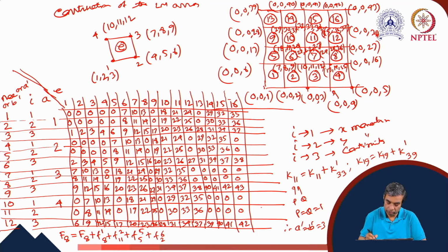Now, I already told you that these values are actually capital P values. So now we have understood that for a multidimensional problem, using the LM array, we can easily perform the assembly process. I have told you KPQ will be 0 if P and Q do not belong to the same element, and we easily understand that there will be lots of terms where KPQ equals 0, so this 43 by 43 assembled matrix will certainly be a massively sparse matrix.